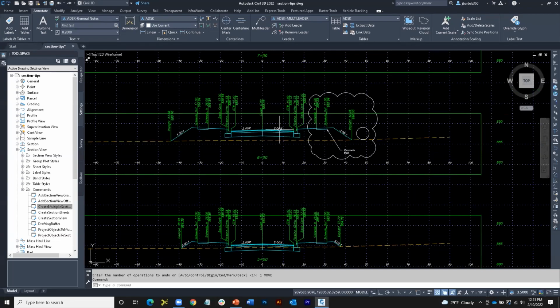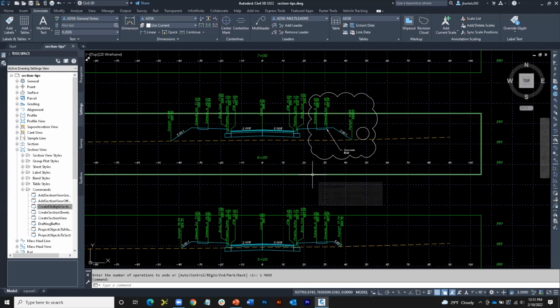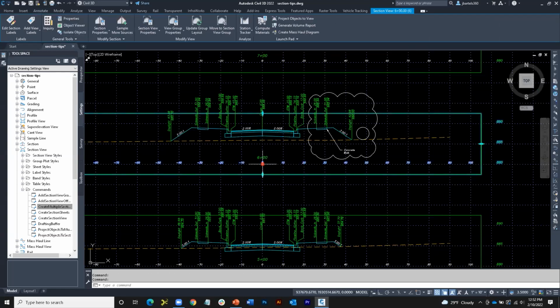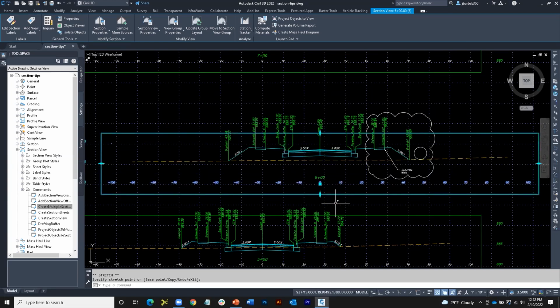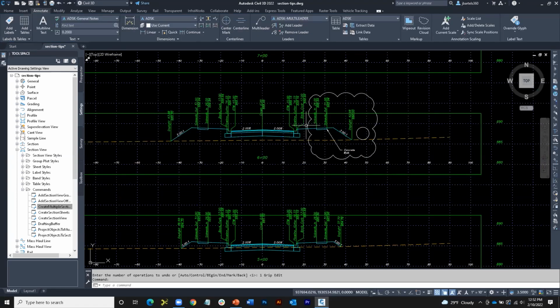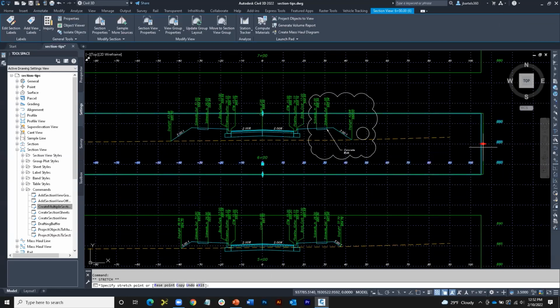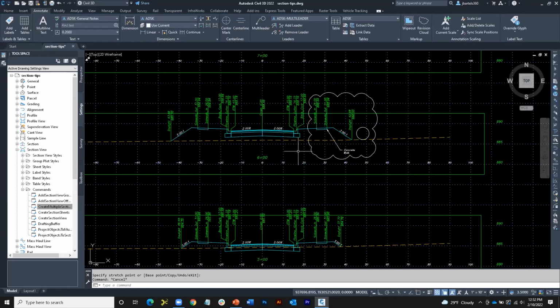Let's undo. Another way you can move a section is by selecting it, and there's a grip down here. It's treated like a handle. I can use that to move that around. Let's undo. These section view buffers have grips so that you can expand or contract them such that they can get around the manual items that you have created. And it's just a really nice tool if you do create manual geometry and things shift around, that makes sure